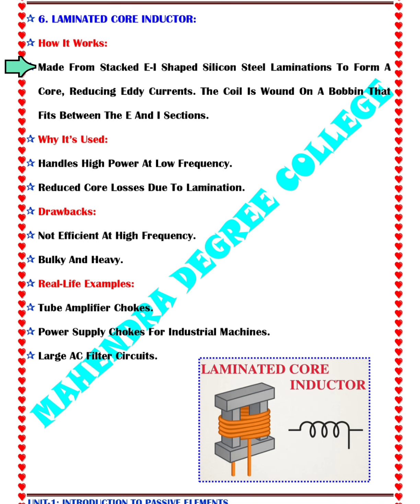Reduce eddy currents. It means eddy currents, these are loops of current induced inside a conductor when it is exposed to a changing magnetic field. By using thin laminations instead of a solid core, eddy currents are restricted to each thin layer, minimizing eddy energy losses.